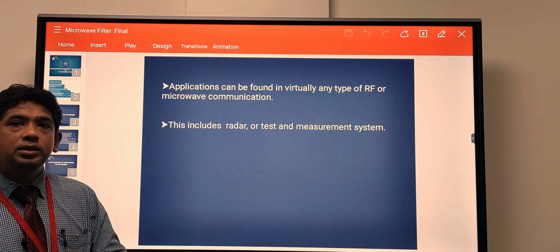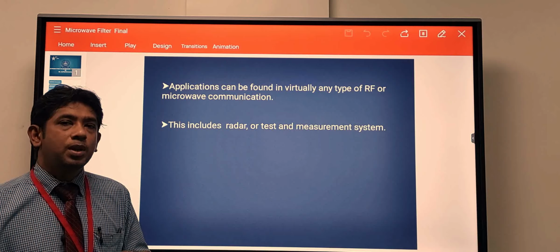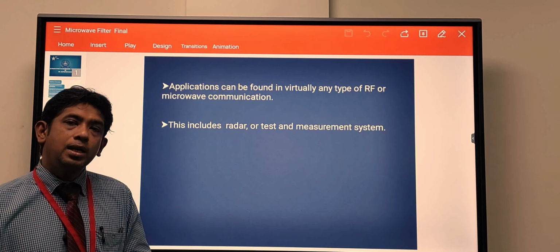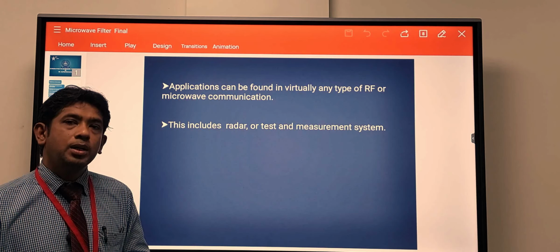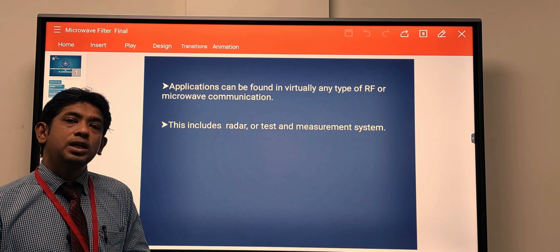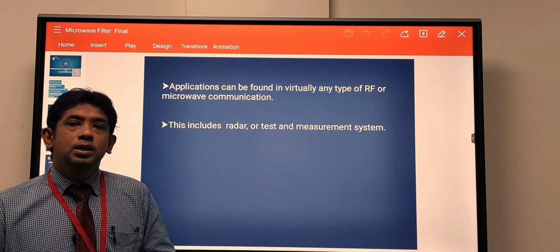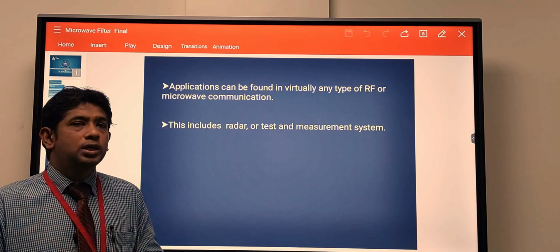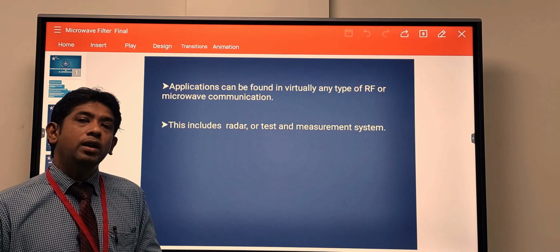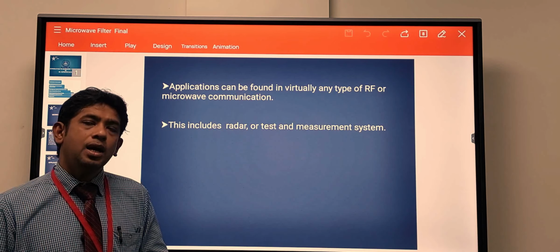Filters designed using the image parameter method consist of a cascade of simpler two-port filter sections to provide the desired cutoff frequencies and attenuation characteristics, but do not allow the specification of a particular frequency response over the complete operating range. Thus, although the procedure is relatively simple, the design of filters by the image parameter method often must be iterated many times to achieve the desired results.